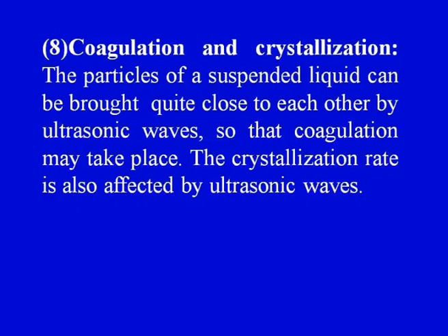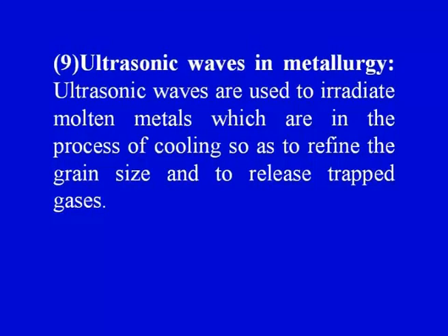Coagulation and crystallization. The particles of a suspended liquid can be brought quite close to each other by ultrasonic waves, so that coagulation may take place. The crystallization rate is also affected. Ultrasonic waves in metallurgy, another use there. These waves are used to irradiate molten metals which are in the process of cooling, so as to refine the grain size and to release trapped gases.